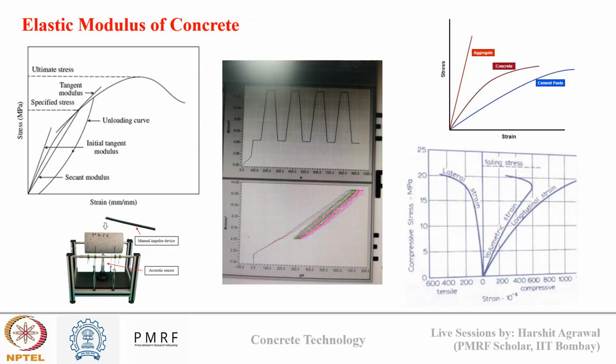So last week we concluded the ninth week of the course where we continued our discussion on mechanical properties of concrete by discussing about modulus of elasticity of concrete. In this we discussed what is modulus of elasticity. Basically it is the ratio of stress versus strain in the linear elastic region. Then we discussed why concrete shows a non-linear inelastic behavior in a stress strain relation.